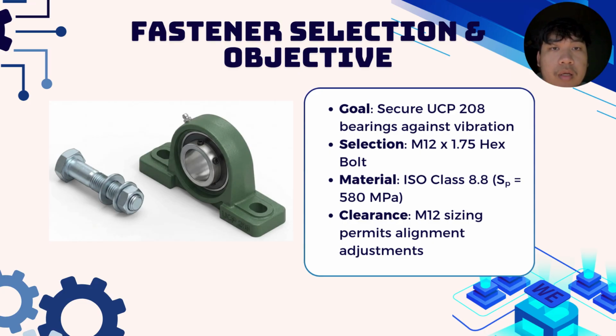We specified an ISO class 8.8 material, which is a quenched and tempered medium carbon steel. This will provide a solid proof strength of 580 megapascal. While the bearing housing can actually fit a 14 millimeter bolt, we stepped down to an M12 to allow some clearance for alignment adjustment. To compensate for the clearance, our design requires a standard hardened flat washer to ensure the clamping load is distributed evenly across the mounting slot.